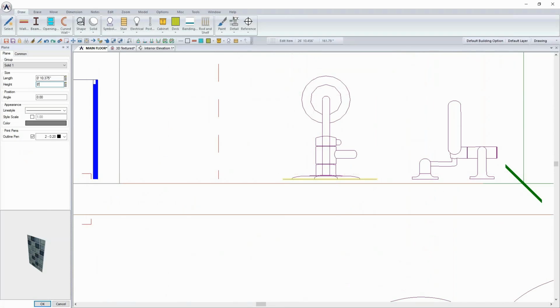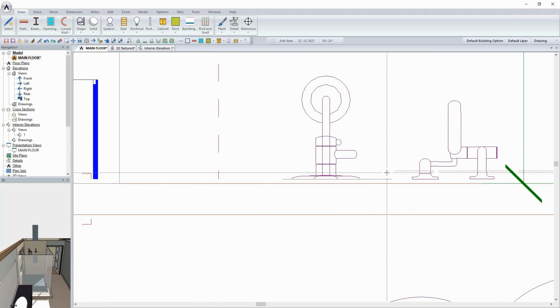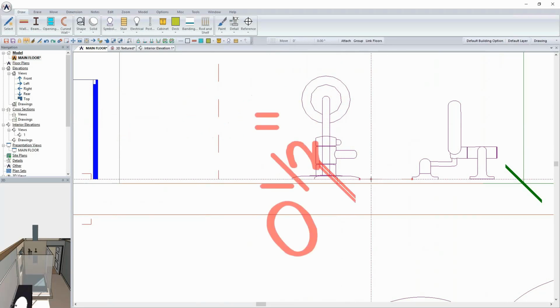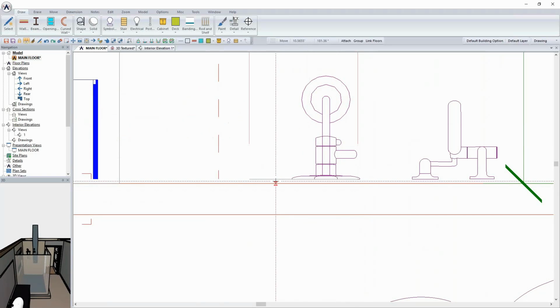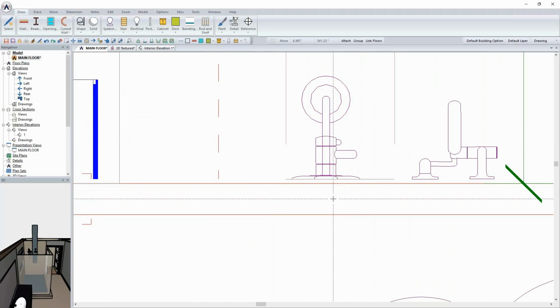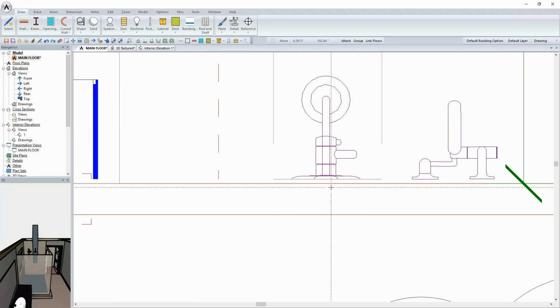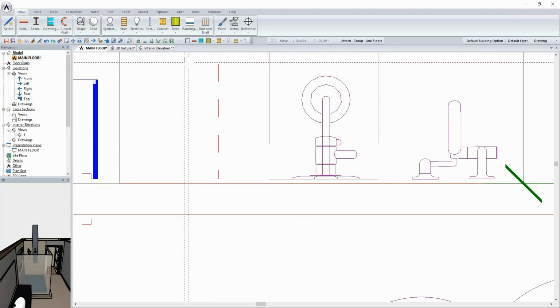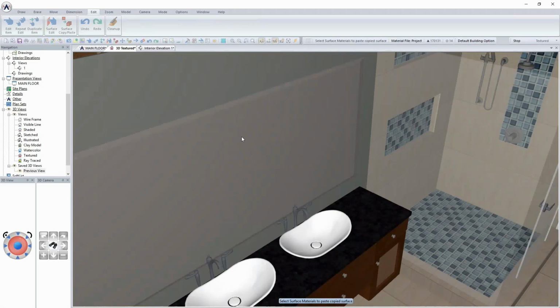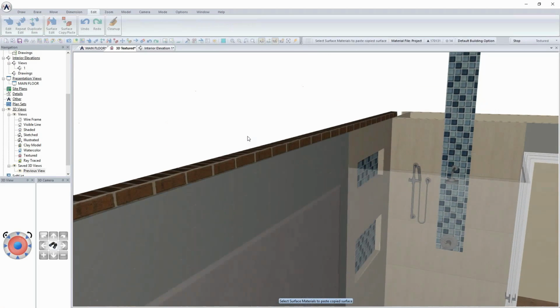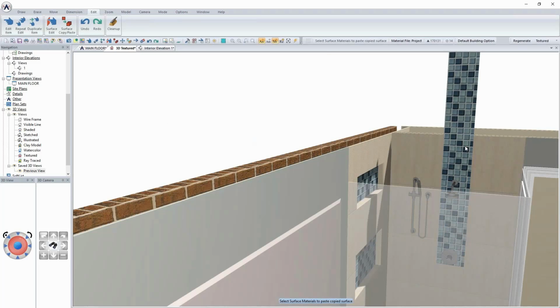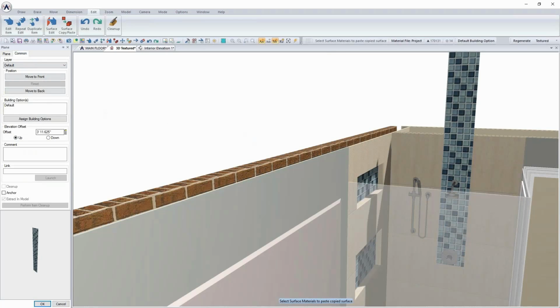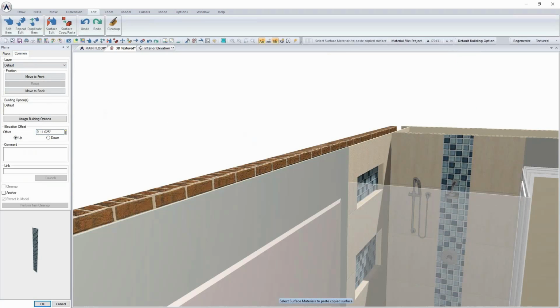All right, and the width, we'll just make it 12 inches, let's say, and I can always center that on the actual drawing itself. And so I pick the center line, and just move it into place where I want it to be. And as I come back into the 3D, okay, it maintained the offset of what we had, so I need to just edit this. If I go into the common, the offset really just needs to be 11.65 inches.